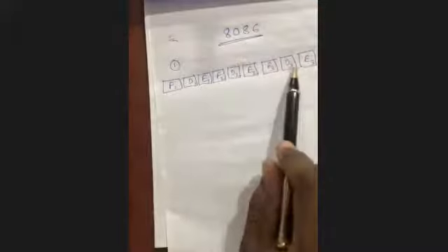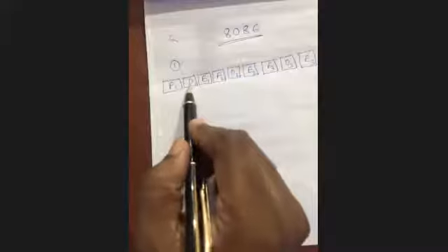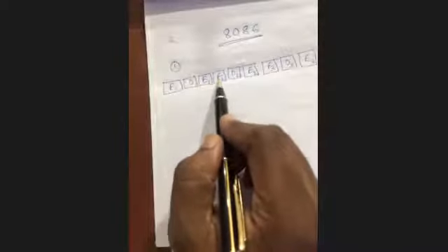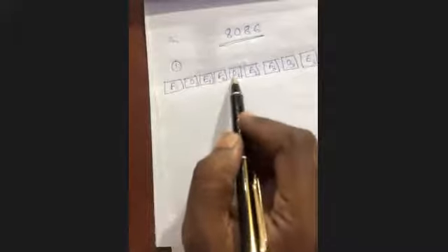Fetching, decoding, execution; fetching, decoding, execution; fetching, decoding, execution. One after another. That's why 8085 is called a sequential IC. It means one job is done, then the second job. Decoding is done, then the execution. After this execution, the second instruction's fetching will be done, then decoding, then execution. One after another. Is it clear?